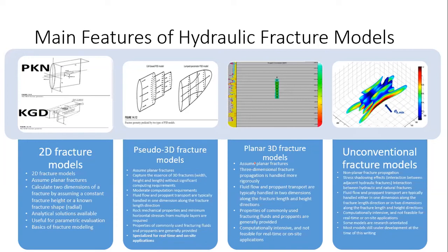In special projects where you have time to design your job and discuss a special reservoir fracturing, and take your time, not day by day frac. If your operation is very, very slow, you can go to the full 3D model, where the reservoir is divided into 3D grids and distributed properties, and all details are included in fracturing.